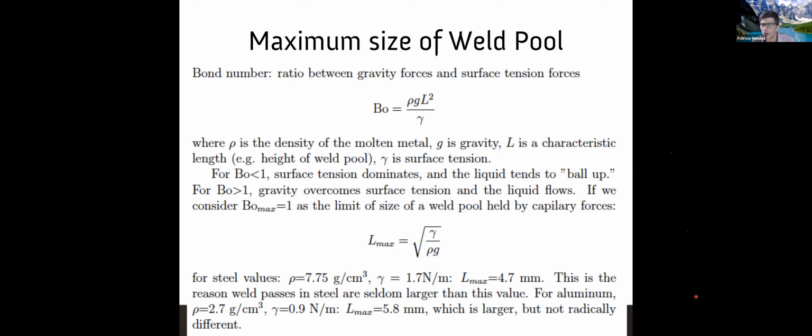So I want to go over some of the questions. I have a suggestion that reduced gravity would cause reduced penetration. Penetration has quite little to do with gravity. I'm going to discuss this in the next slides, although I acknowledge that if you flip the weld and you're doing overhead, you tend to have less penetration, but that's typically because the weld bead is smaller, because you don't want it to fall on you.